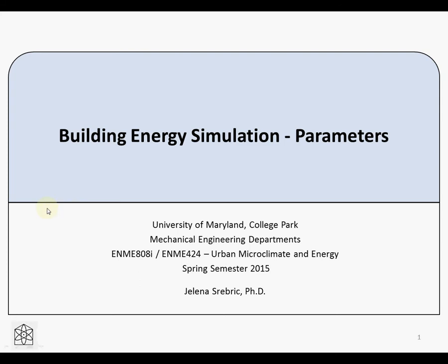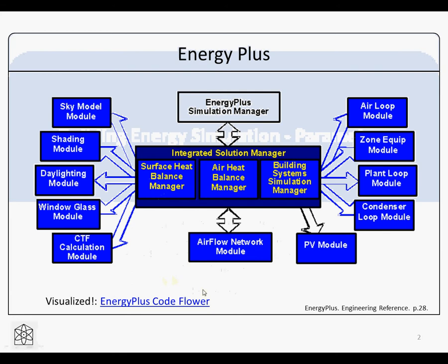Before I do that, I'll talk a bit about how EnergyPlus does some of the calculations. So, look a bit under the hood of EnergyPlus, and that will help us determine what parameters we're going to want to look at. As I had mentioned in the prior lecture, EnergyPlus is a simultaneous integrated solver. So we have our weather information, information about the windows and the walls and surface heat balances, and we can combine that with information about our HVAC equipment and how that's distributed in the building.